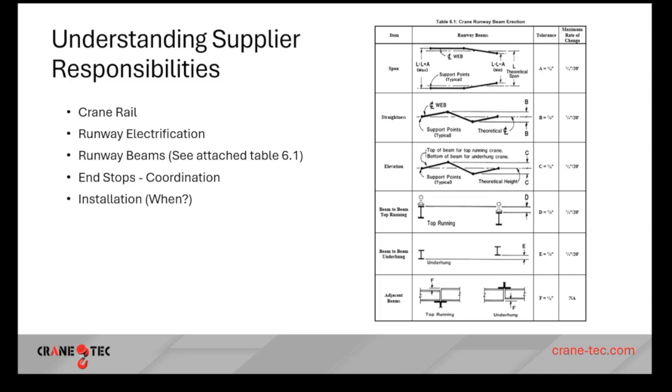But yes, there have been occasions where I've had a contractor not supply to the 3/8 inch tolerance on his runway beams because his building was so far out, and we've gotten the engineers involved to help come up with a solution, whether that solution is web stiffeners or something else.